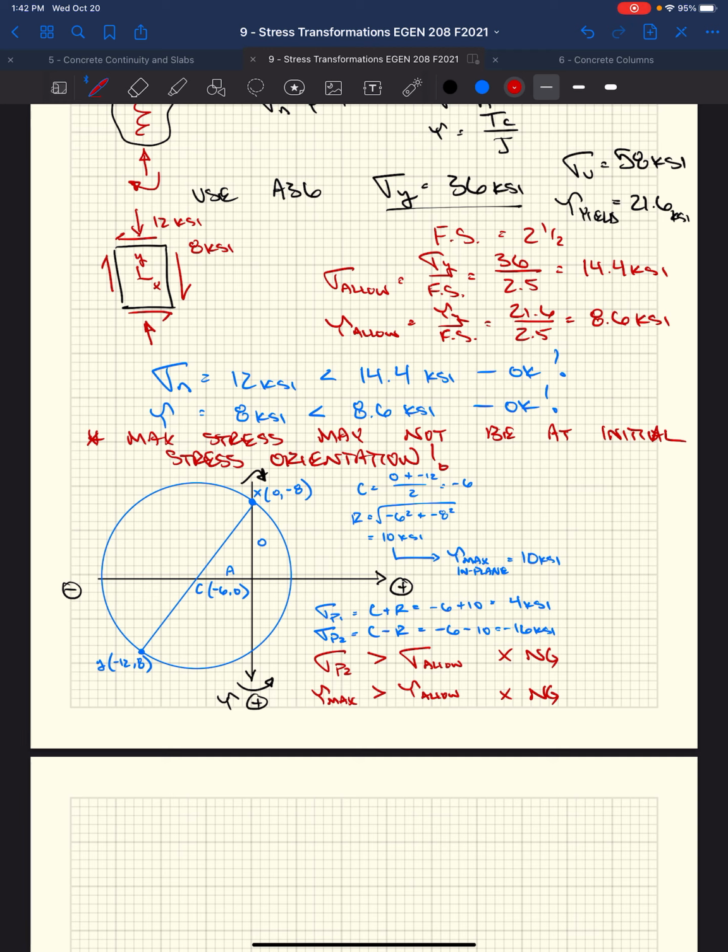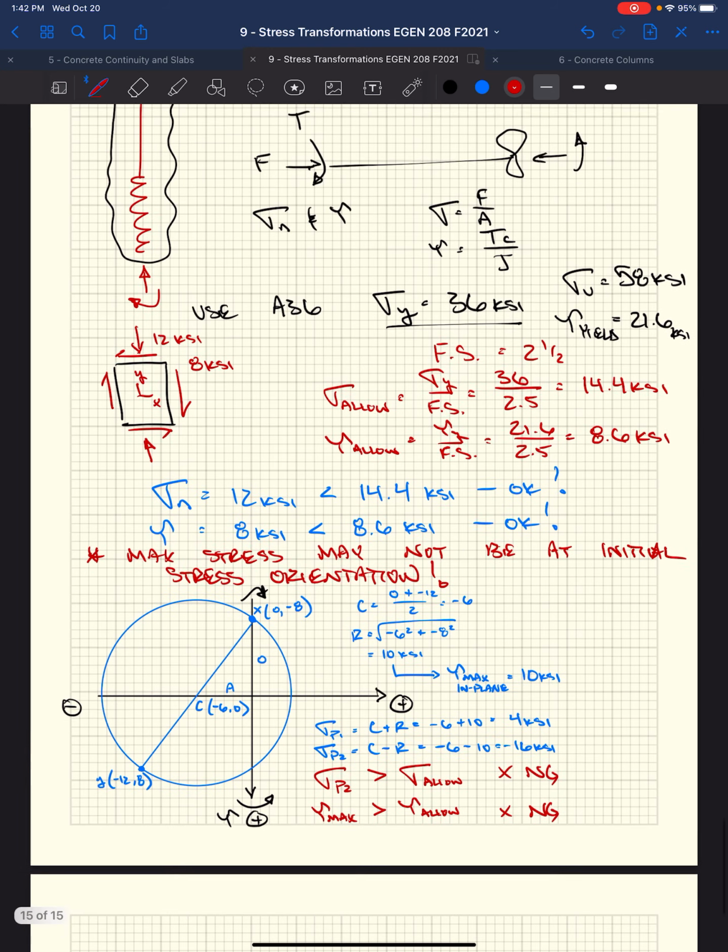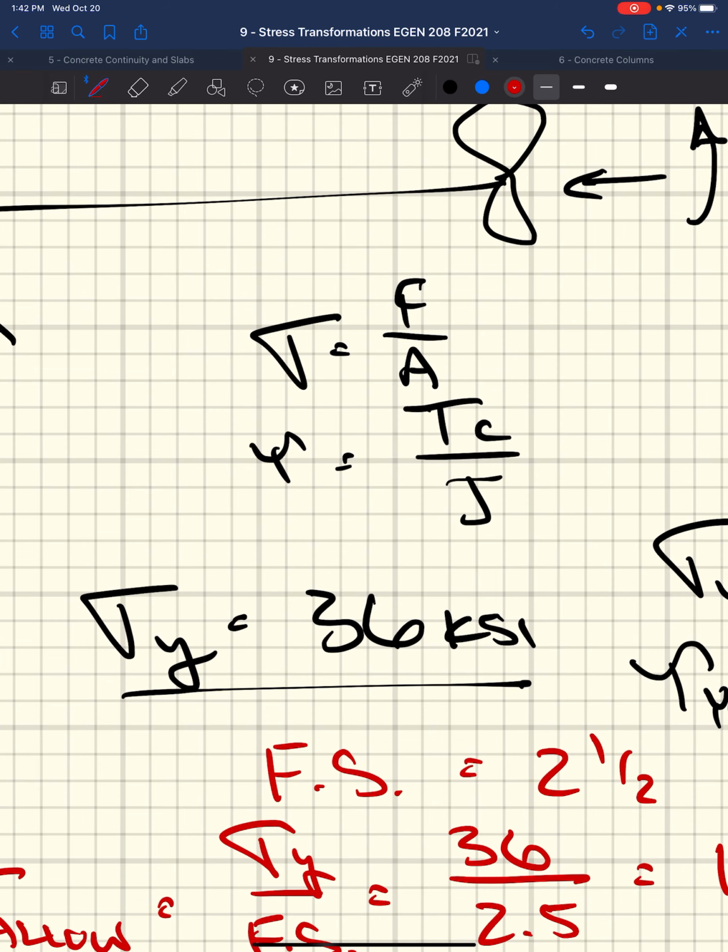So in this case, if we were looking at this drill stem or this propeller shaft, we got to the conclusion that it's overstressed, and I don't feel good about it, right? You could do a number of things. We could use a 514 plate, which has a yield stress of 100 KSI. Or you could go back and change the geometric properties. We could change our polar moment of inertia, which is a function of our radius, in order to reduce the stress in the shaft.